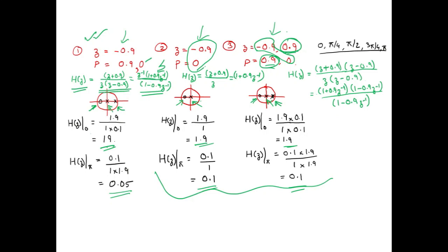Okay. Similarly, over here also you have the transfer function given, and at last, we have this as the transfer function. Now it is interesting to see over here that you will be very tempted to cancel out this one and this one when you are trying to calculate the poles and the zeros.